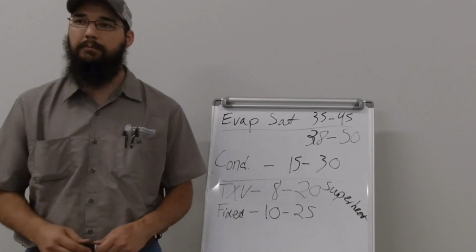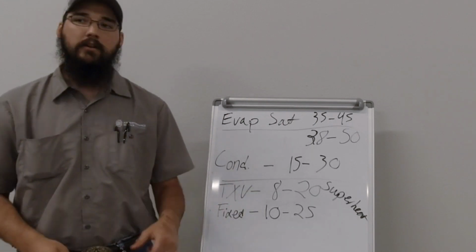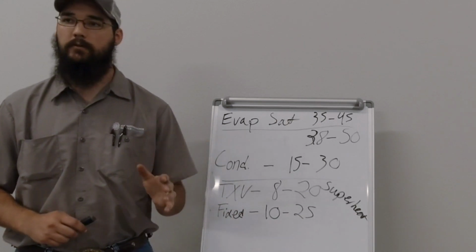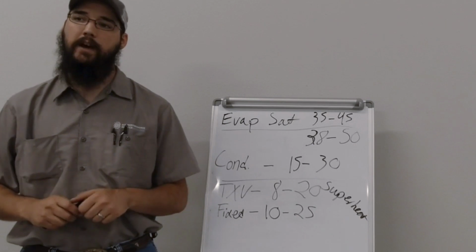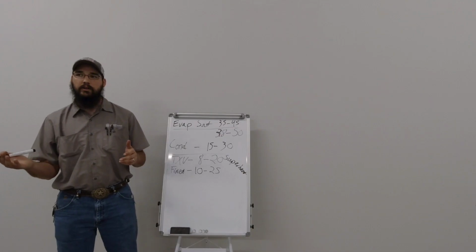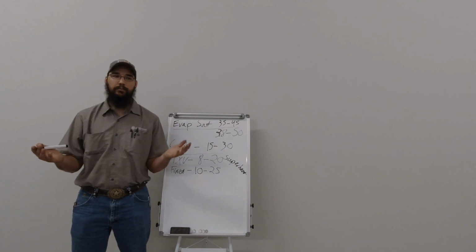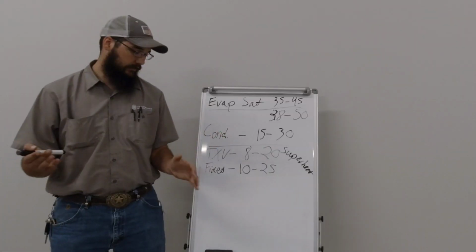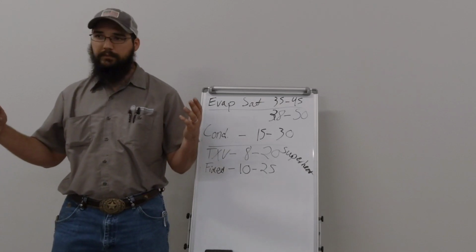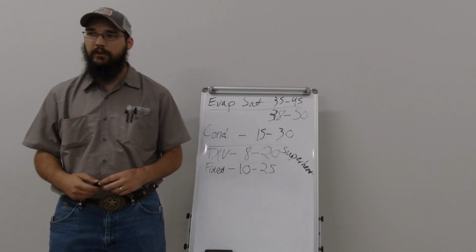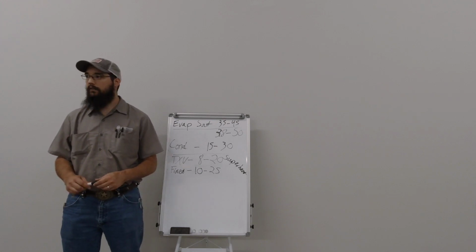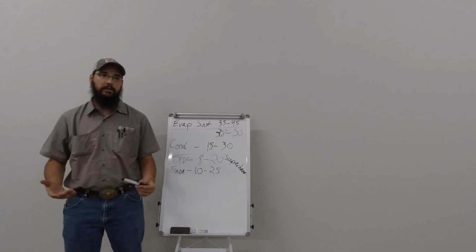It controls that temperature. On a fixed bore, it becomes really critical to look at the load on that coil, which is where that wet bulb factor comes in. And if you have a high load, you've got to calculate a higher superheat. If you try to charge a 10-degree superheat at an 80-degree return, chances are by the time you get down to 72, you're not going to have a compressor for very long. You're going to start flooding back.